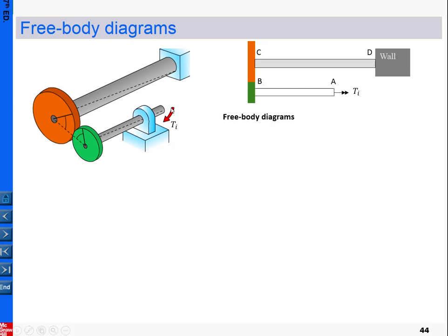So here, for fundamental mechanics of materials, at the free end we apply a torque. The torque is transmitted to the shaft, in turn to the gears, in turn to the other shaft, and this shaft on the other end is fixed against the wall. And this wall is basically a simulation of a very big load, like the transmission from engine to wheels. But basically here we are assuming this wall is clamped.